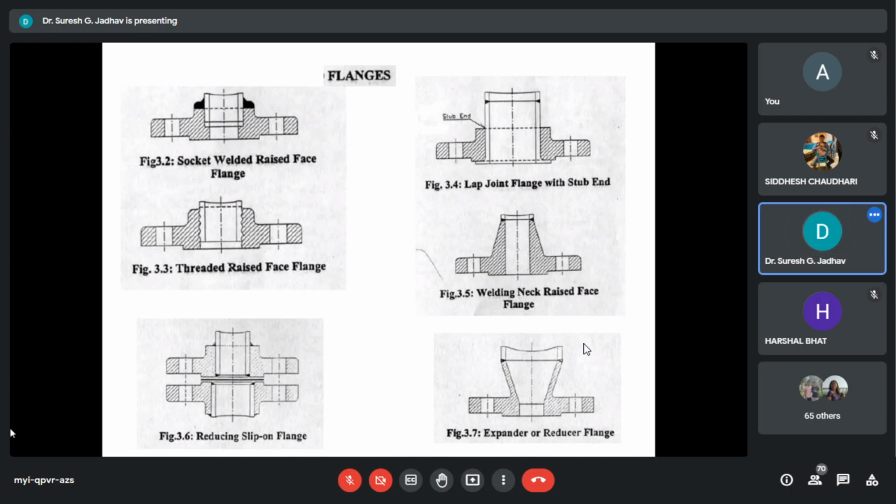A flange joint is composed of three separate and independent, though interrelated components: the flanges, the gaskets, and the bolting, which are assembled by yet another influence, the fitter. Special controls are required in the selection and application of all these elements to attain a joint which has strength for different applications.